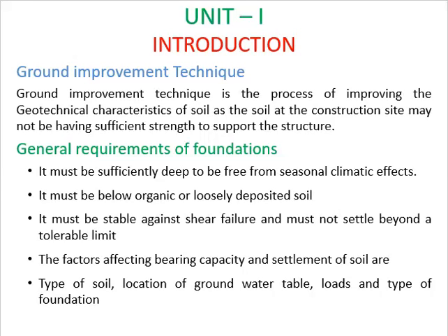If the soil is loosely deposited, it will be subjected to either shear failure or excessive settlement. To avoid this, it has to be compacted to the required density using the suitable compaction method. If the top layer is having organic matter which is weak in strength, or if the soil is contaminated, proper care should be taken to avoid failures.